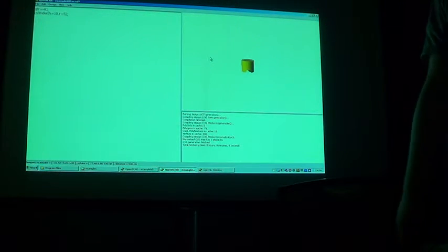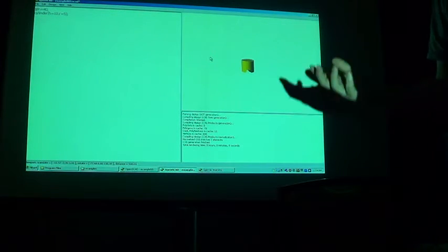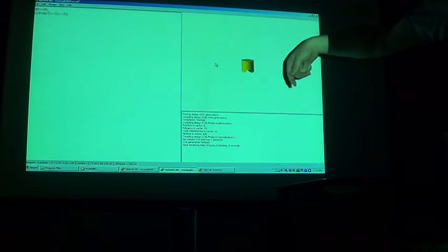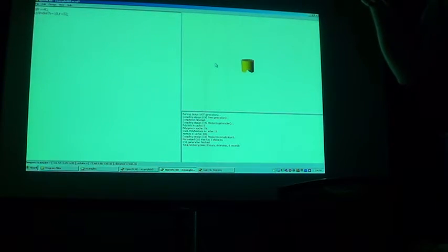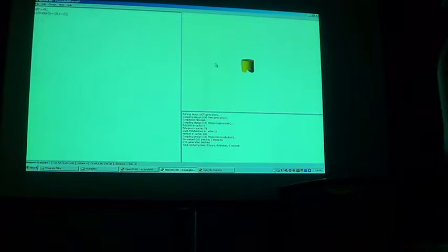Again, at the default setting, I want to say it's 20 as the default. You probably won't notice it unless you're printing a really big object, and then you'll see the sides. But the moment you start adding more vertices to the outside, it will take longer to generate the G-code. It will take longer to print because it's doing very fine motions around the outside then. So we can do things like that.